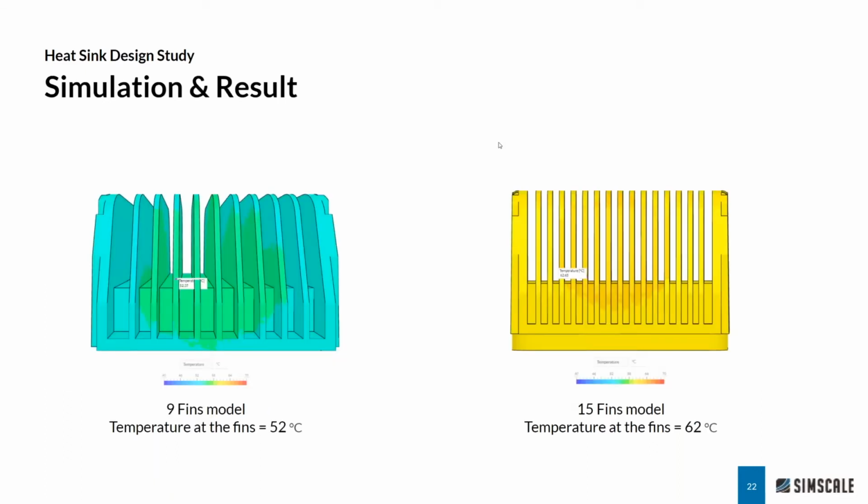So here are some results. I'm going to sort of dive into the results here, and then we can take a look at the why. On the left, we see, first of all, to start, these 2 have the same legend, right? So I capped the legend at 70 Celsius. And on the left, we have the 9-fin model, which is really showing a temperature around 52 degrees Celsius or so on the fins. It is sort of a teal, so it's cooler than the one on the right.